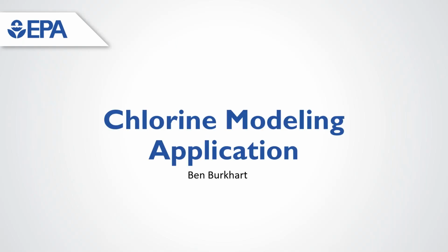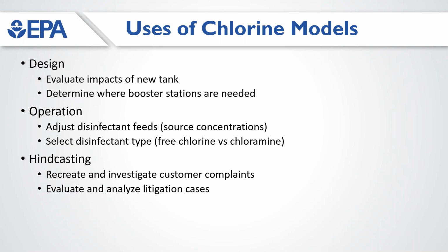So now it's time for our last application, chlorine modeling. Chlorine modeling is commonly used and has many different application uses. Like water age, it can simulate the effects from adding or removing components like tanks, but the effects are only for the modeled disinfectant. Chlorine modeling can show areas with lower than acceptable concentrations and can help find the best locations to add booster stations.